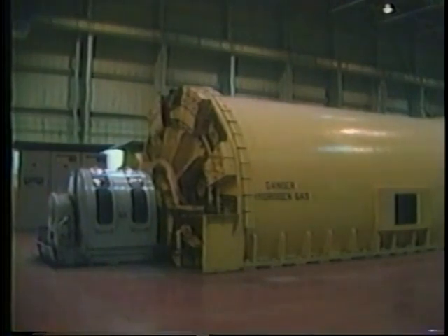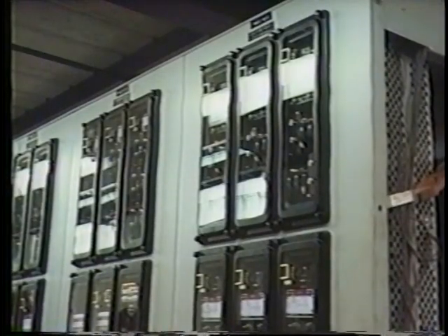In practice, it is probable that the generator automatic controls may attempt to increase generator internal voltage in order to compensate for some of the voltage drop downstream. However, this would take some seconds and therefore should not interfere with the operation of protection relays, nor with our studies of fault characteristics.